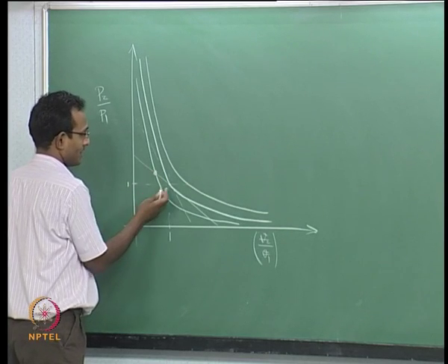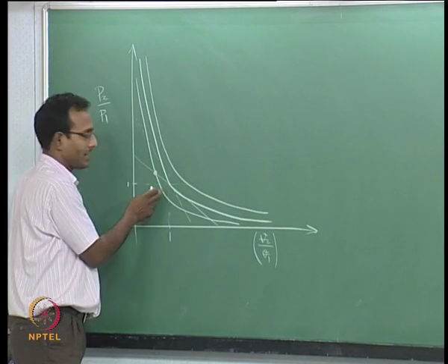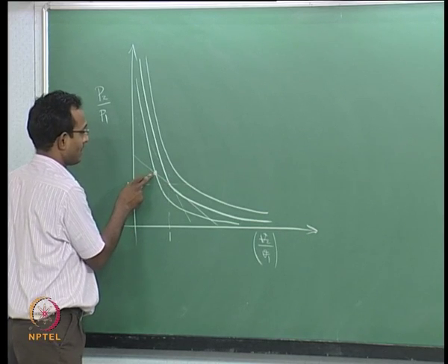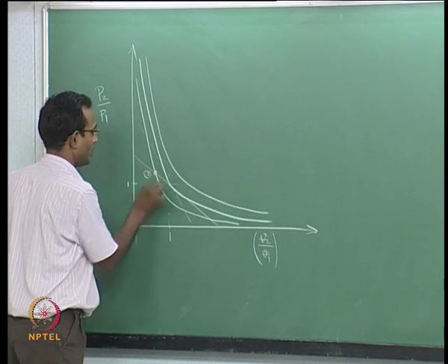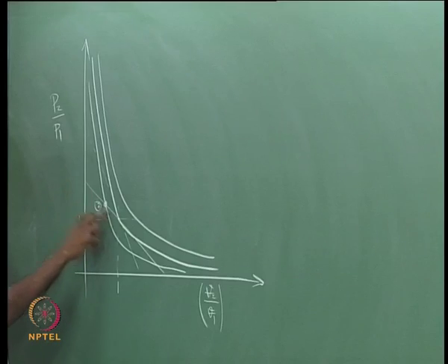If I cool with this particular q value, then I will end up with this particular state 2, for that particular beginning Mach number M1. If I heat it, I find that I am not going to have a solution for that particular Mach number. We will figure out what is happening in here in detail as we go.